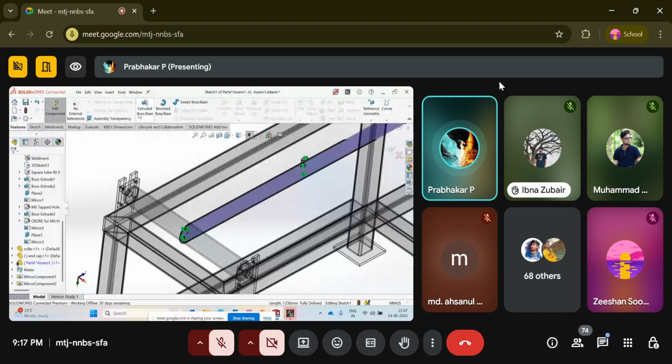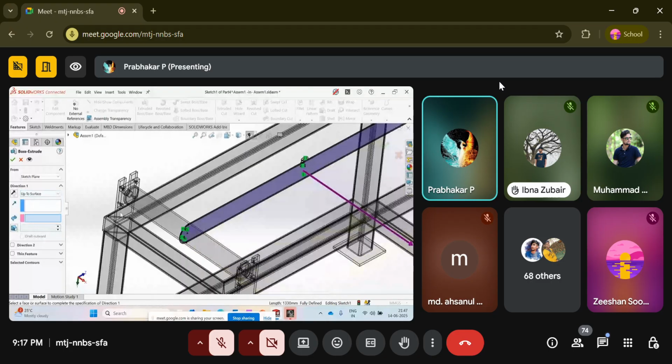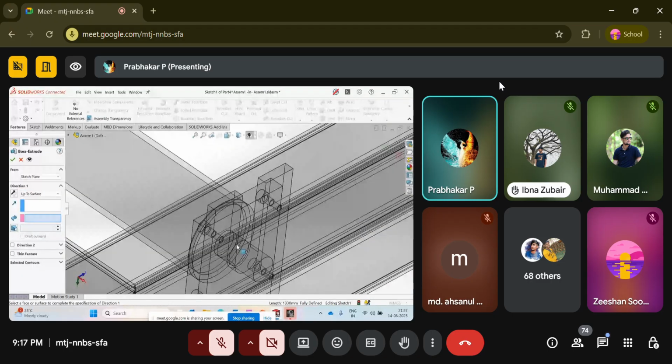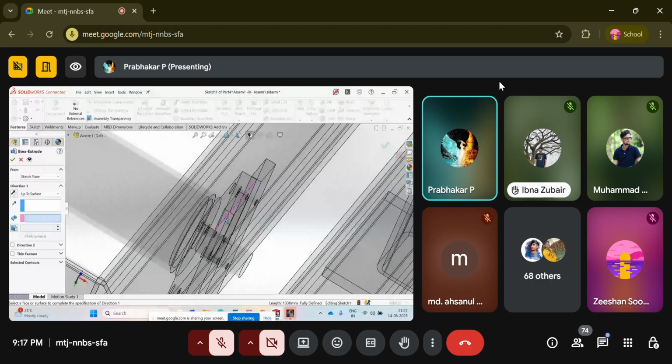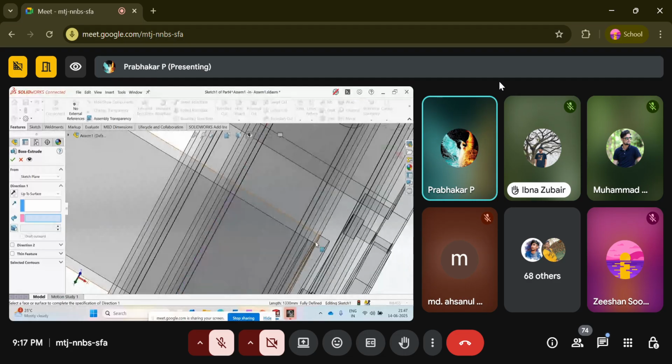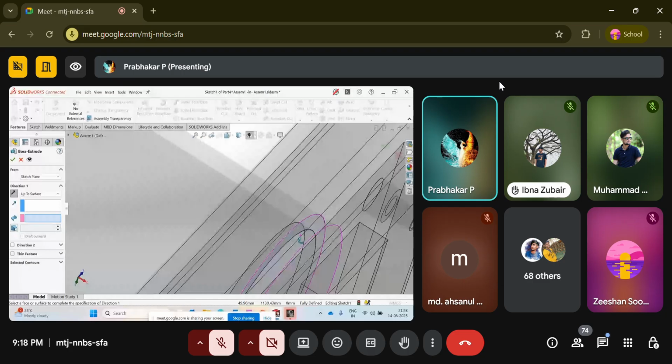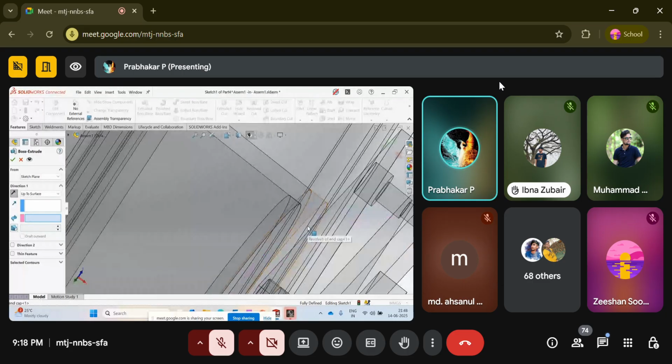Earlier I used blind, where I gave a dimension. Now I give up to surface, and select this surface. Okay, I'll do one thing.